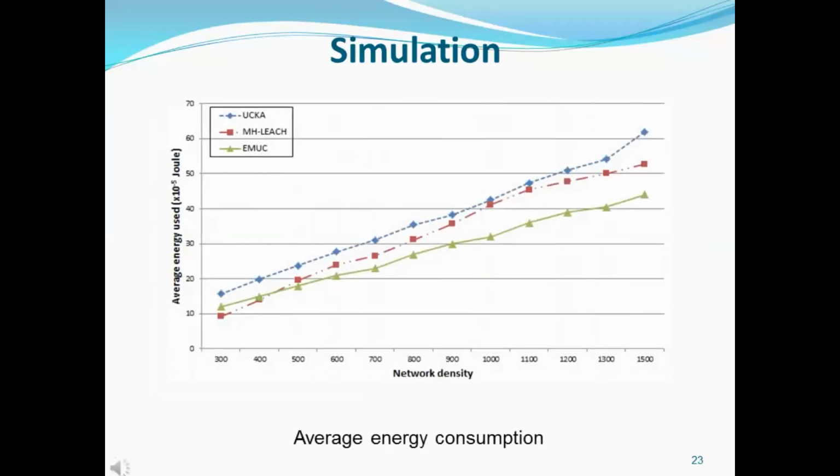The following figure illustrates the average energy consumed by network devices during the clustering phase in the short term. We observe that the energy required for the clustering increases along with the network density due to the amount of messages that need to be exchanged to generate the topology. Our proposed approach consumes more energy compared to the other approaches. This point may be assessed as a shortcoming. However, the results are acceptable because the consideration of the state of health in the weight metric displays better performance in the long term.